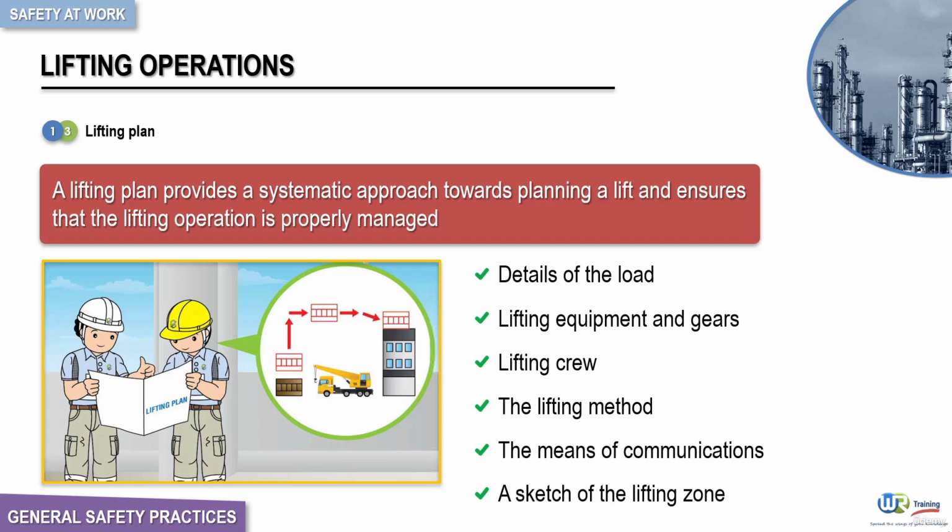Once the lifting plan has been established and approved, you should never deviate or vary from the approved version. So keep in mind, if the actual information at the lifting site does not comply with the lifting plan, you should stop the operation until the plan has been updated and reapproved.